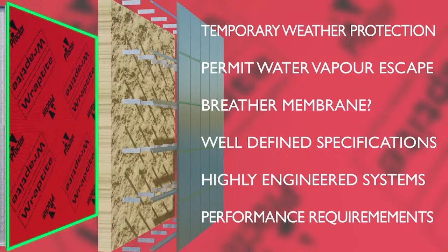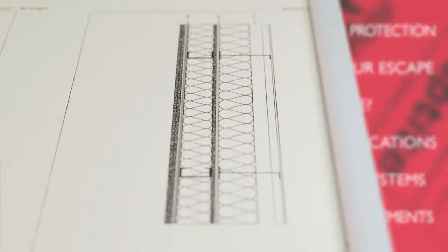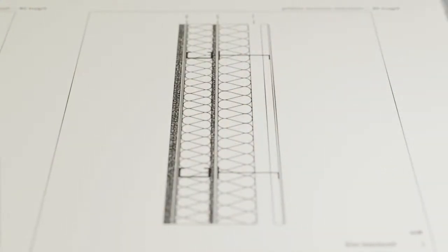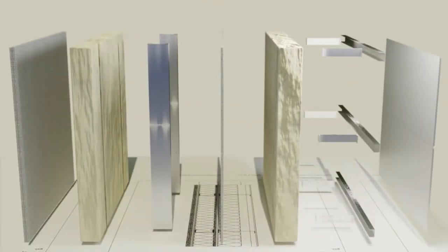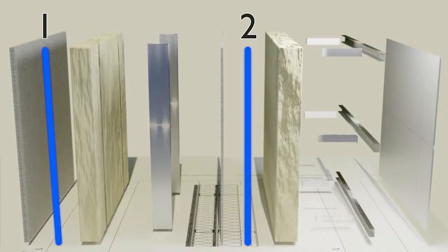To illustrate the placement of membranes within a facade wall, GD40 takes two examples from BS 5250. The base wall is of SFS construction, with sheathing over the steel frame and insulation placed both between the frame and continuously over the sheathing. The document then considers both open and closed jointed facade cladding to the outside, with a ventilated void behind. In this wall construction, there are three possible membrane locations. On the warm side of the insulation being the internal lining, over the sheathing between the two layers of insulation, and outside the insulation layers in the ventilated cavity.